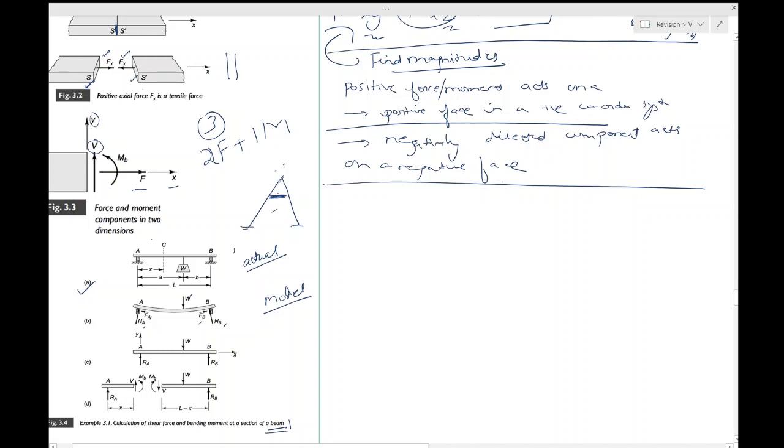We can say that the friction forces are limited by the static coefficient of friction. That we already knew from Coulomb's law, that the friction force is limited by mu N, where mu is the static friction coefficient. When the coefficient of friction is small, we can be satisfied that the friction forces will be small compared with the normal forces. So here's the idea. Fa at its maximum will be equal to mu Na or mu Nb, whichever way you take.